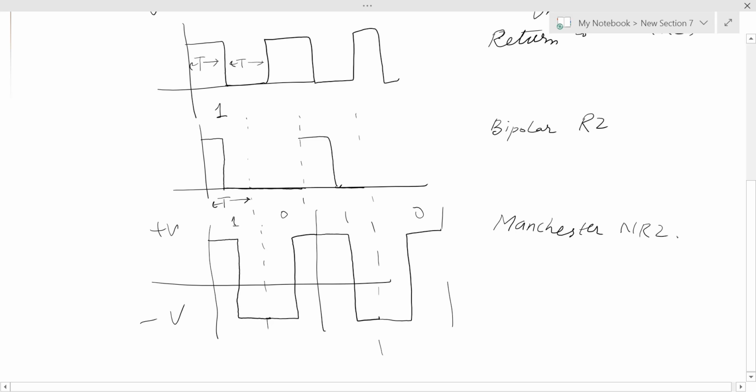Okay. So with an input from our previous lecture, where we proved that a train of rectangular pulses has a power spectral density which has a flavor of sinc function, all of these signals, if you plot their power spectral densities, will have a flavor of sinc functions. We will not prove it, but we will take it as a fact that these different combinations, like non-return to 0, return to 0, then bipolar and polar, have some effect on the bandwidth of those signals.